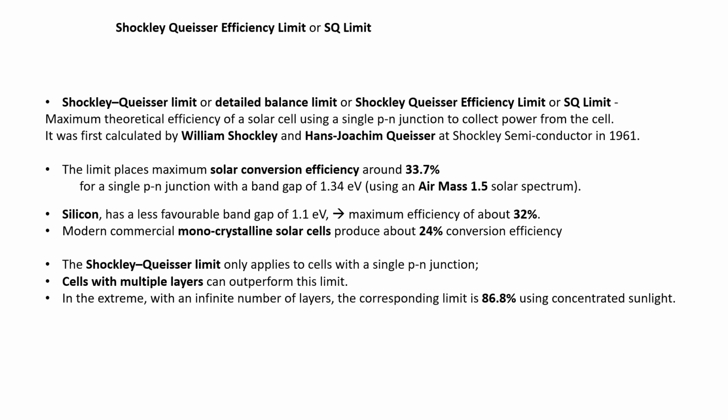For space, the air mass is taken as 0. This means of all the power contained in sunlight falling on an ideal solar cell, about 1000 watts per square meter, only 33.7% of that would ever be turned into electricity, that is 337 watts per square meter.